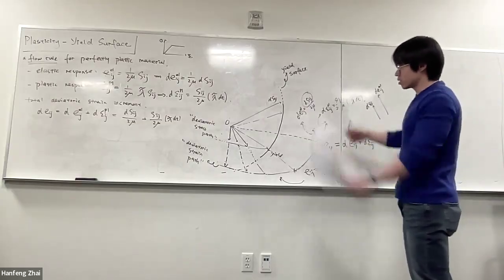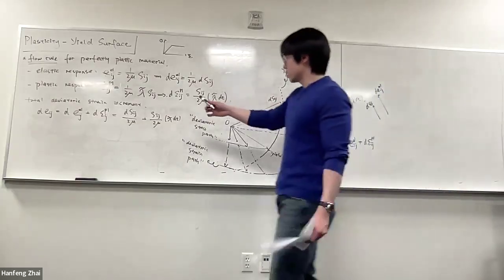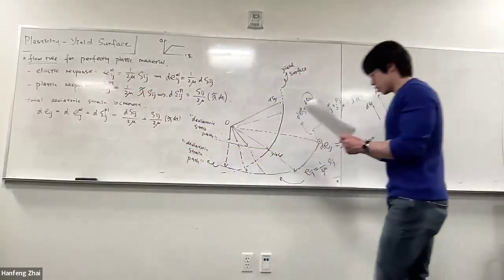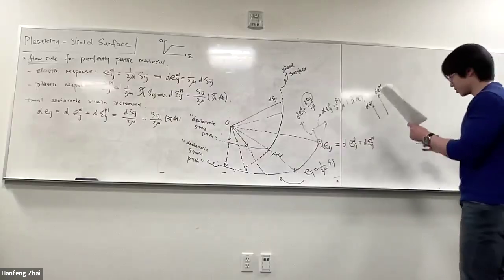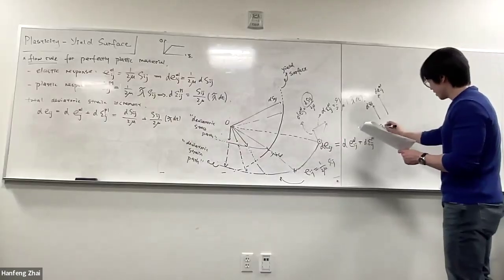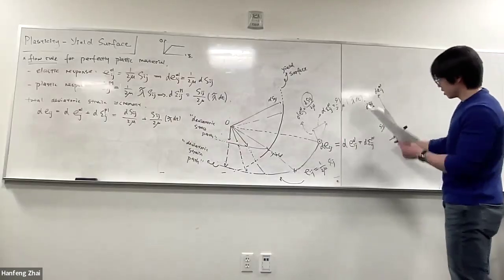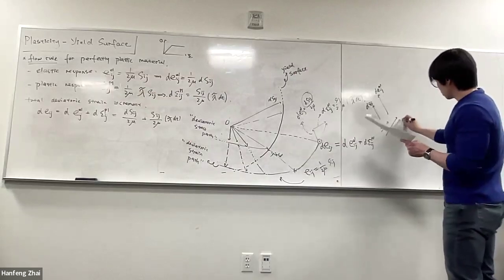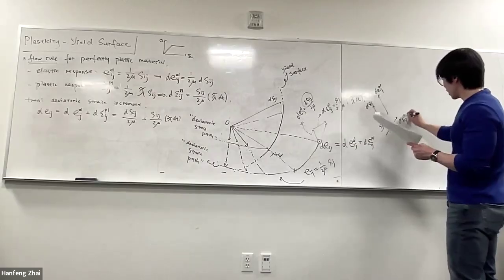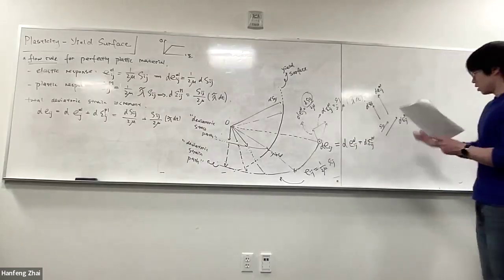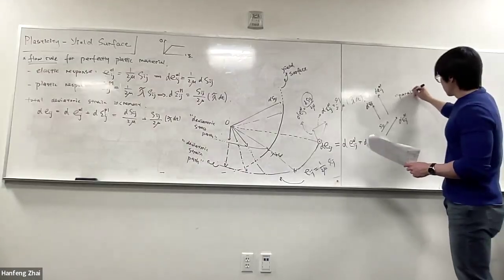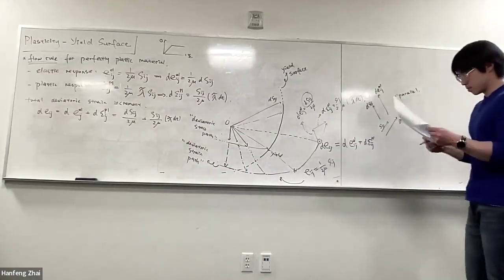They're in the same direction because we start by specifying the plastic strain rate, as I repeated probably 100 times, right? So this is S_ij, the direction of S_ij. Then according to this equation, d epsilon_ij plastic, the propagation of the plastic deformation, is parallel. So these are parallel.